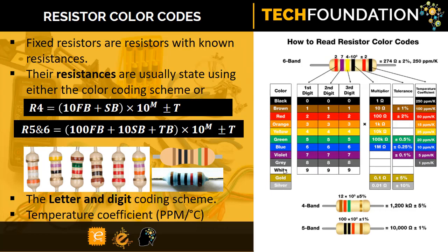Okay, so let's try and calculate the resistance of this first resistor here. This is the first band. Take note, this is gold, and you can't have gold as a first band, at least for this case. So we have orange, white, orange. So let's come to the table. In the table, orange is 3.